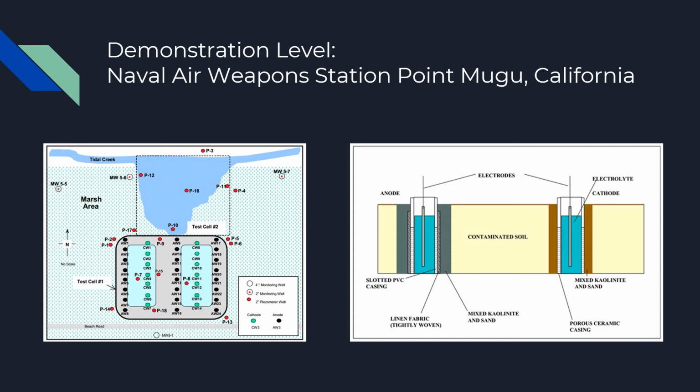Remediation. Before starting the remediation process, many laboratory tests were conducted with the soil samples from the site. These included testing for contaminant and soil characteristics, grain size distribution analysis, pH, total organic carbon, toxicity characteristic leaching procedure, cation exchange capacity, and hydraulic conductivity. These tests were followed by determination of electrode placement, migration rates, electrolyte requirements, removal efficiency, and power requirements.